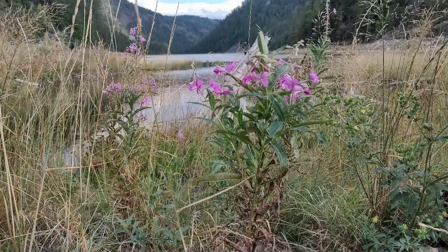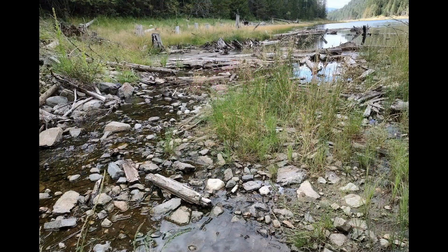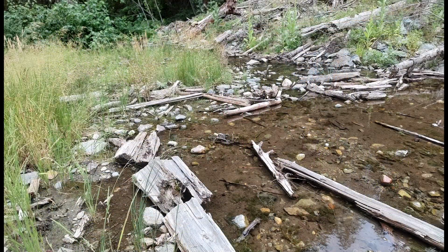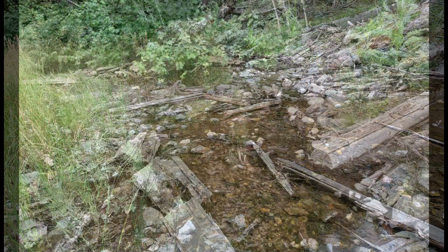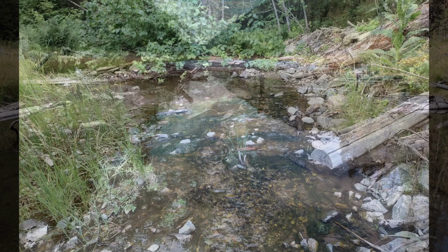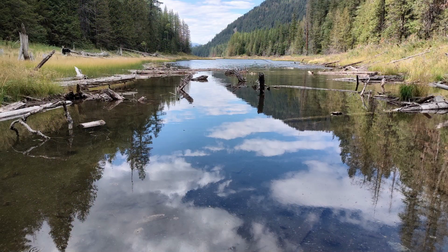I'd like to show how the Violin Lake Restoration Project looked on August 12, 2023, almost 2 years after the project was completed. This is where Goodeve Creek begins, where the inside toe of the dam had been removed. Grass is growing on the restored floodplain of Goodeve Creek. Here is where the restored Goodeve Creek flows over the buried vertical grade control structure that was made from rock. The water level in Violin Lake is now the same as before the dam was built over 100 years ago.